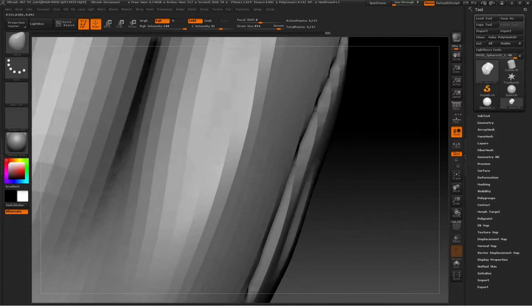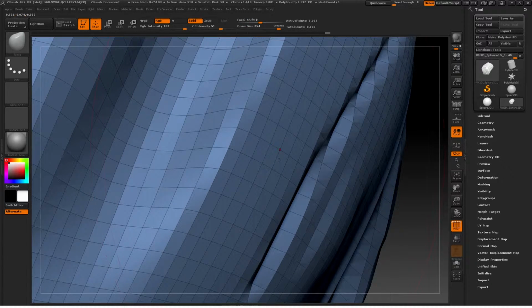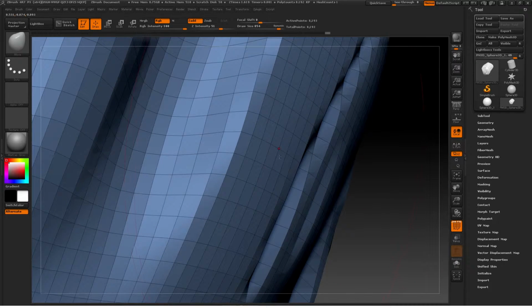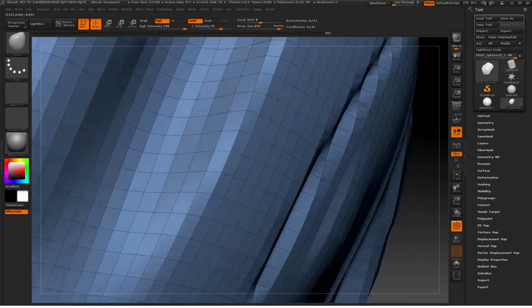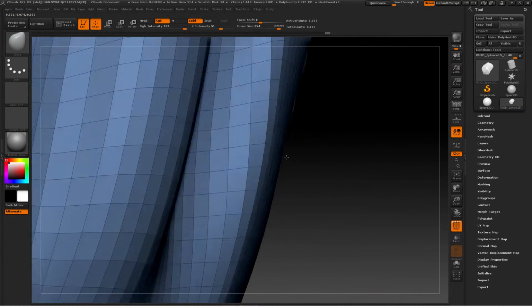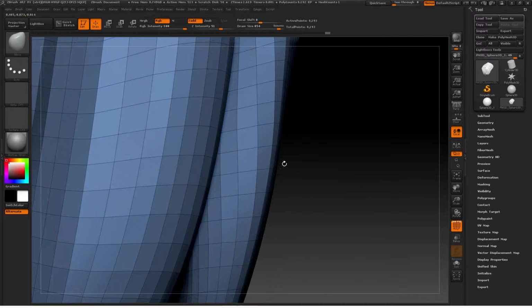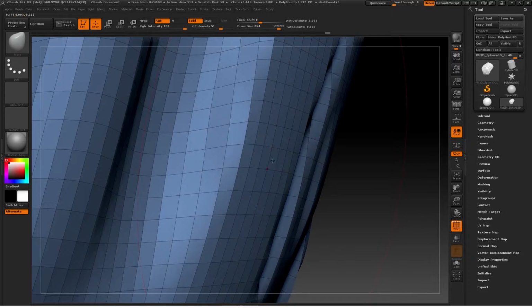If you invert it, what happens is that you generate a volume from the normals of the polygons that we're working on. In other words, imagine that we have a polygon and we trace a line that's perpendicular to the polygon we have selected. That line would be the normal vector of the polygon, and the Move uses that vector to deform the geometry in that direction if you invert the brush.